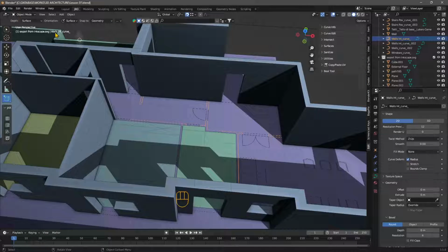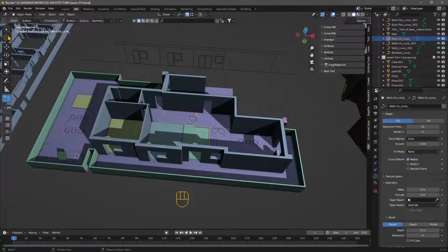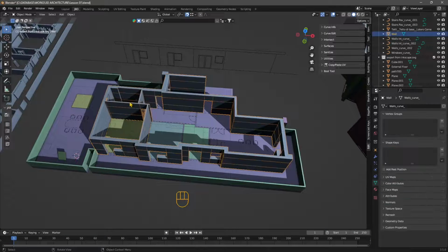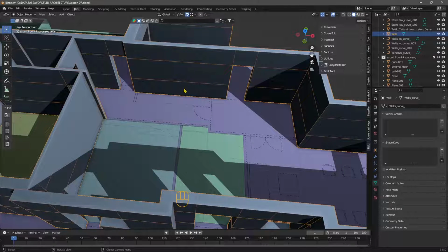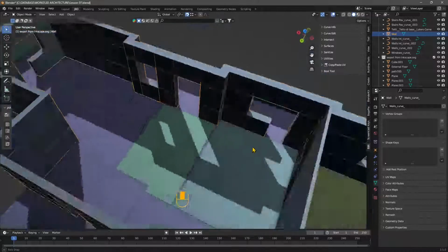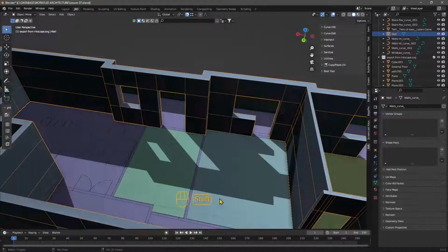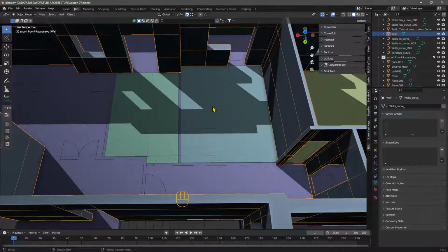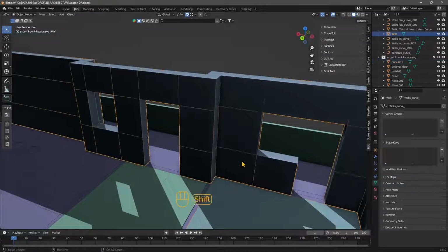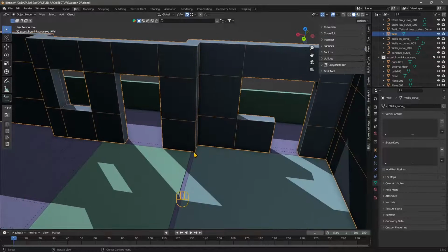So let's say that I don't want to create different walls, but I want an entire model, just like I'm doing here, everything connected, internal and external walls. So I want to start from the external wall, like this one here, and then continue and merge everything together. So we need to cut. We need to have something that can be extruded right here.